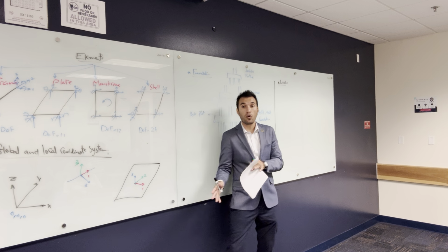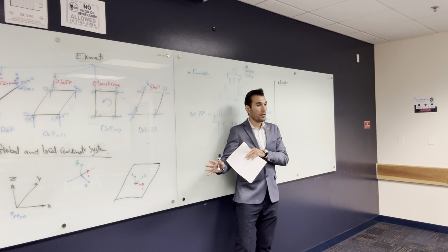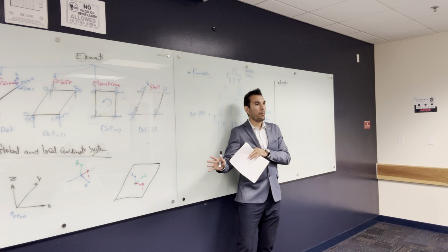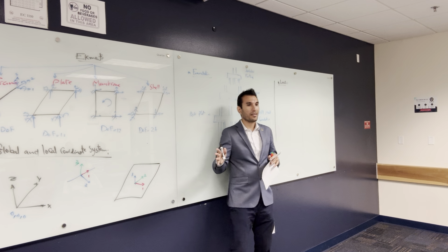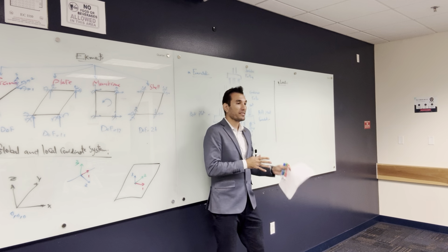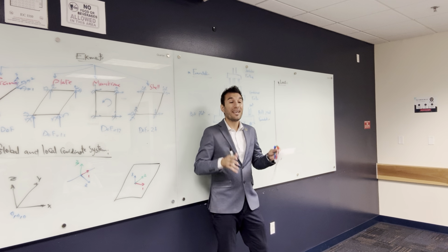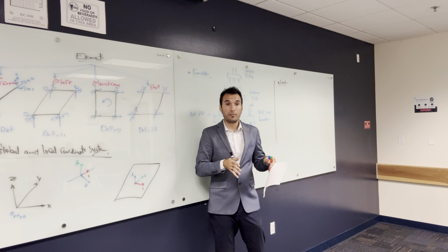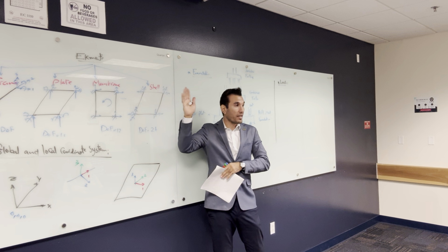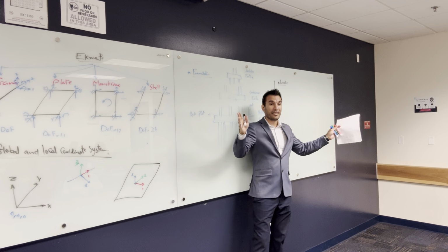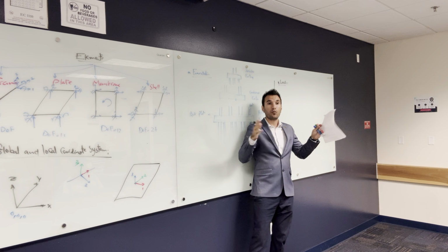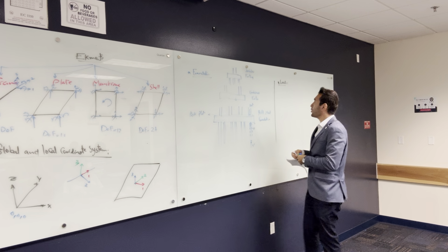They make something called load combinations. They did some statistics and found out that the maximum seismic cannot happen with the maximum wind. You can have seismic and wind at the same time, but not the maximum seismic that can happen in the whole lifetime of the structure, together with the maximum wind. So they made something called load combinations.